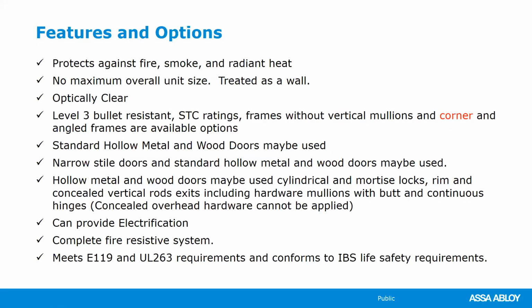So we look at the features and options that we've already discussed for E119 assemblies with glass. It protects against fire, smoke, and the important thing of the radiant heat for both the glass and the frame. There is no maximum overall size because it is tested as a wall. You need to think about it again, treat it as a wall. It's optically clear. You have many different capabilities with it, other than just fire.